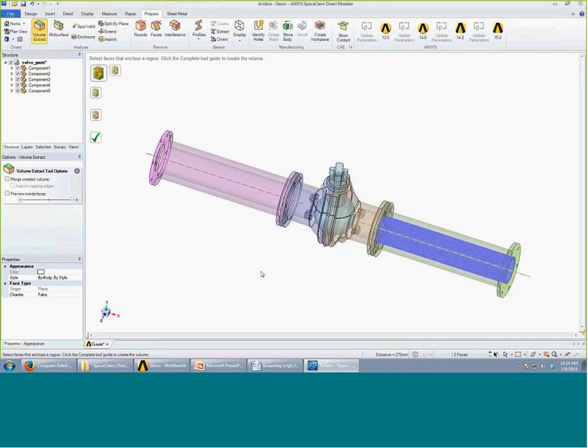And so now it's going to try to essentially go from one opening to the other that I've selected. So if I do the Preview Inside Faces, and I start on my initial side on the right here, and I drag the slider bar here, you can see as I'm dragging it, it's extending that face selection and extending the flow here to show me what my flow domain is going to look like.